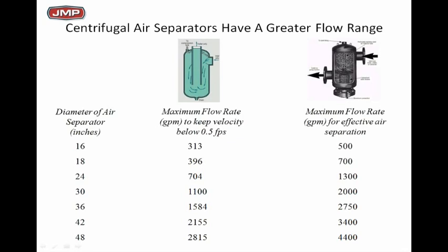So you see the capacity difference. The message is, in your specifications, you should always demand tangential connections to make your air separators work much better. If not, and it's just an inline kind of tank, that inline tank has to be physically bigger to get the velocity down to 0.5 foot per second to get the same air separation capability that a Rolairtrol will give. So this example shows you a 30-inch tank being a Rolairtrol.